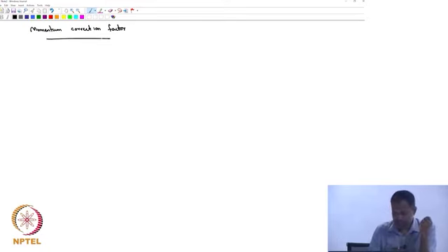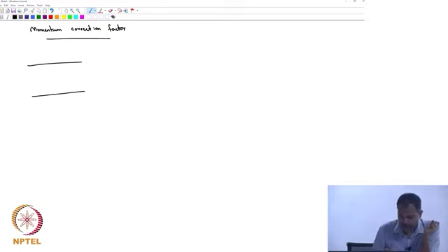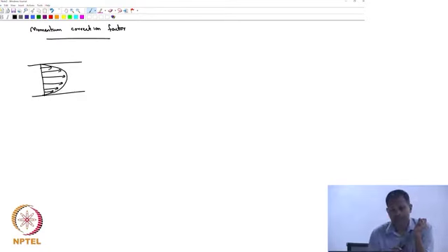The reason is that, let's say we go back to our situation, the pipe flow, where you have fluid flowing fully developed, and you know that the profile is parabolic. Then we define an average velocity as the integral of u dA divided by the integral of dA, where u is the velocity profile. That's what you would have done to calculate your average velocity, right?